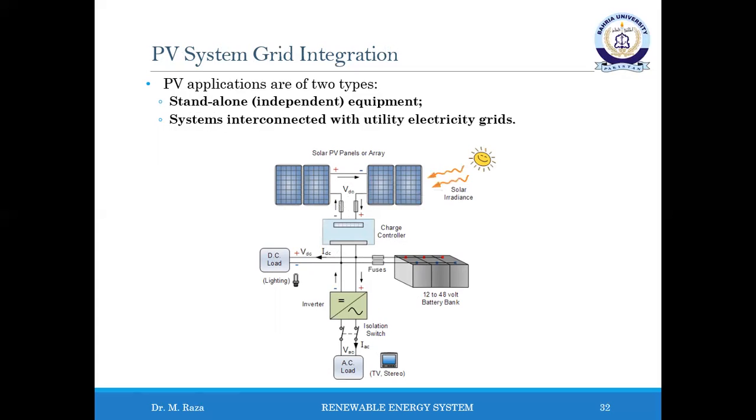In many standalone PV systems, batteries are used for energy storage, as they may account for up to 40% of the overall standalone PV system cost over its lifetime. These batteries cause losses in the PV system due to limited availability of time and energy to recharge the battery, in addition to insufficient battery maintenance.